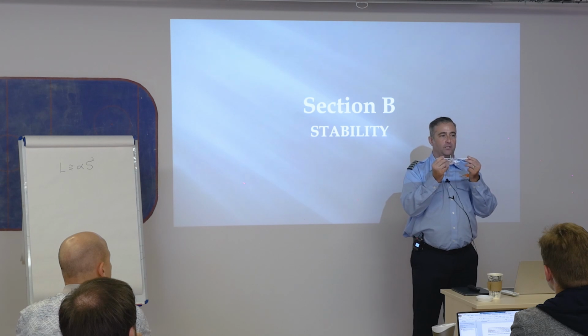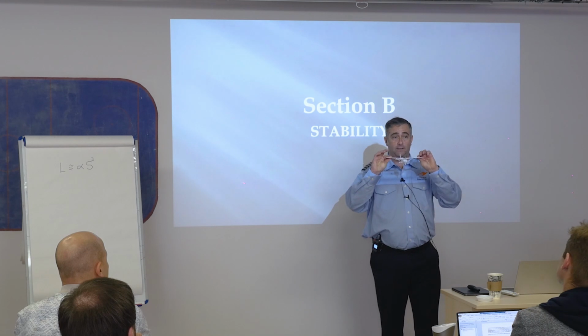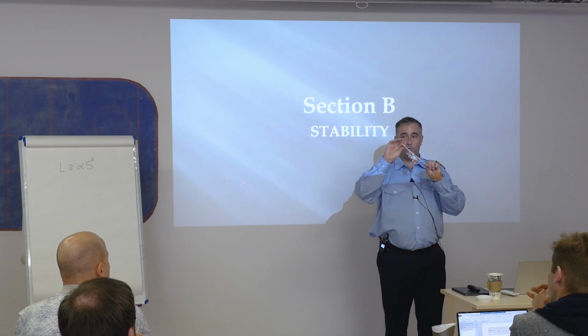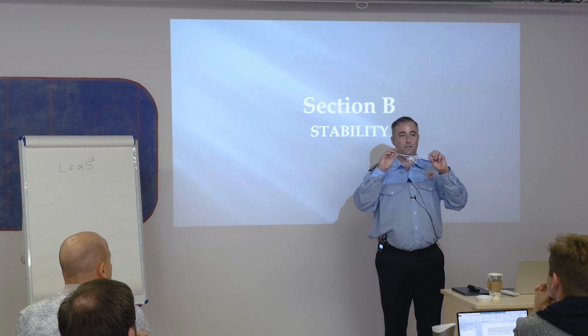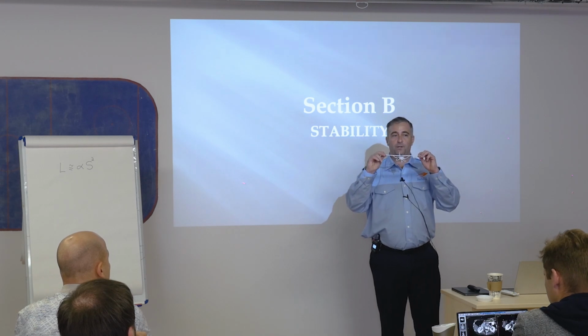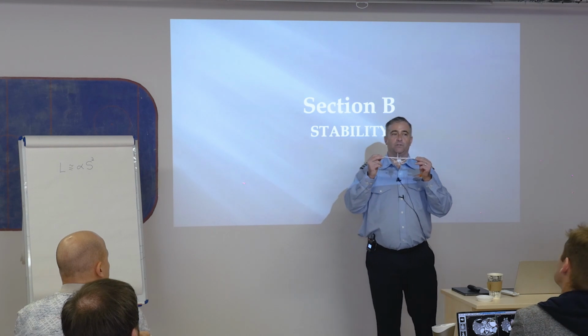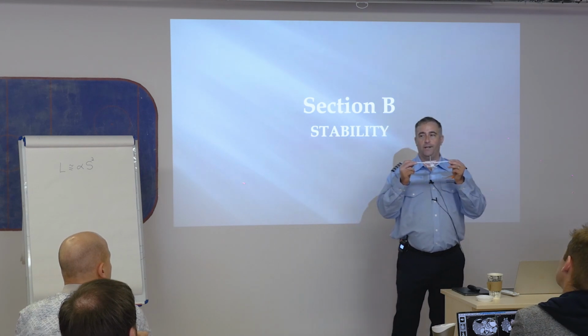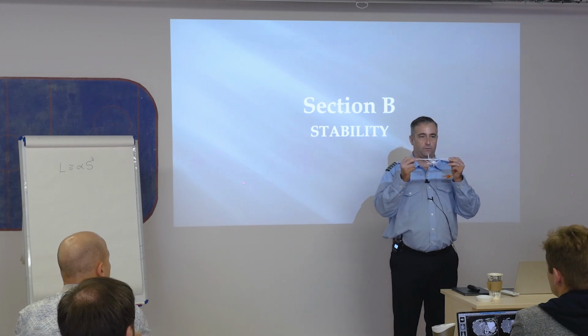And I've got a control surface, and we talked control surfaces yesterday. So we said these are ailerons that are making me move left and right about the longitudinal axis. And then for the vertical axis, I have another control surface. Which one's that? The rudder, okay? So that rudder is going to cause the motion around my vertical axis. There's one more axis. Anybody? Lateral, okay? Everyone okay with the word lateral?